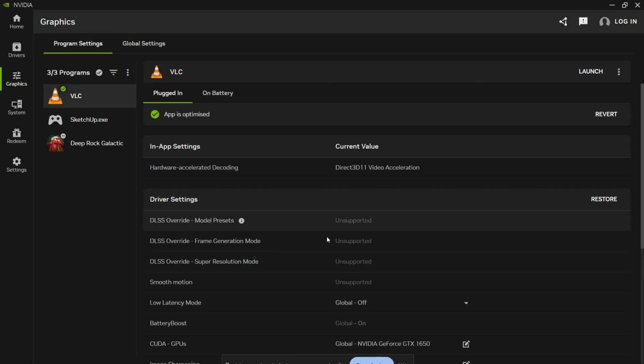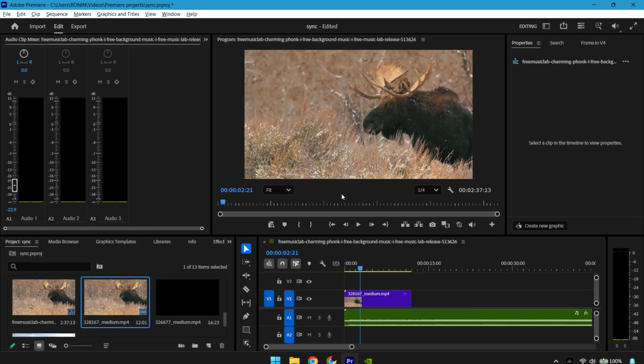At this point, if you followed all 4 fixes, there's a very good chance the error compiling movie error code 3 is already gone. To recap, first switch to software encoding in the export window. Then change the project renderer to Mercury Playback Engine software only. Next, clear the media cache and restart Premiere. And finally, update your graphics drivers and adjust your GPU performance settings if needed. These are the most reliable fixes for this issue, especially when exporting H.264 or H.265 files.